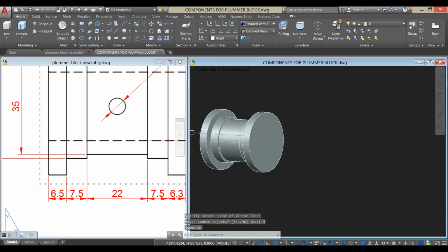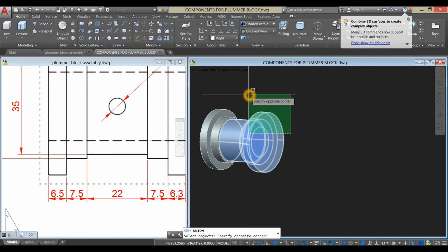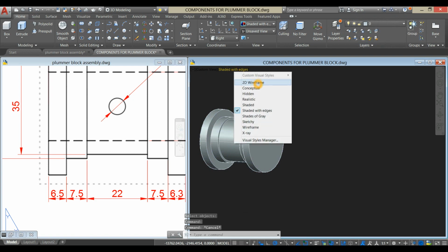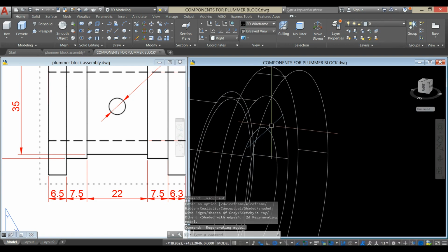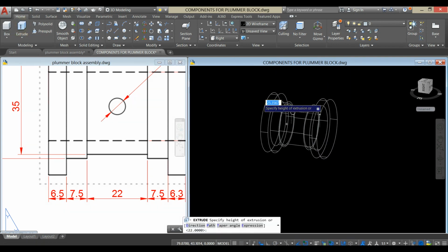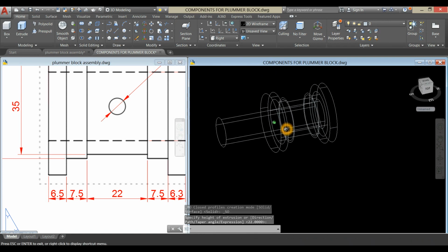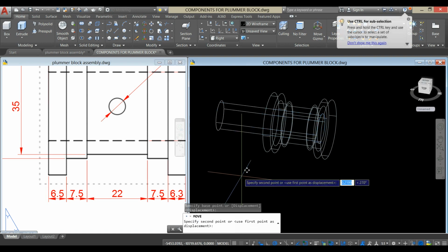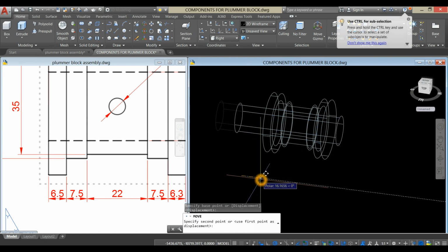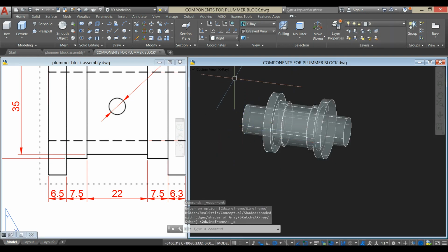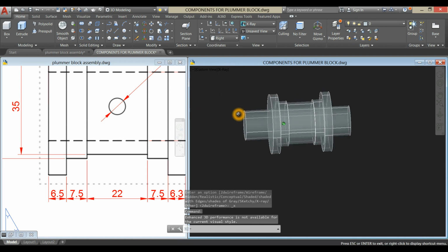We're gonna poke a hole through these objects. So what I'm gonna do is combine all these objects first and then change this to 2D wireframe. I'm gonna grab or highlight this smallest circle and extrude it up to this point. It has to go through all the objects so we can poke a hole. Move it a little bit. I'm gonna change this to X-ray for better visualization.